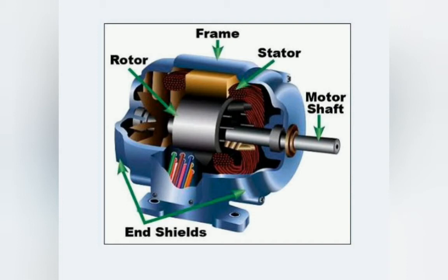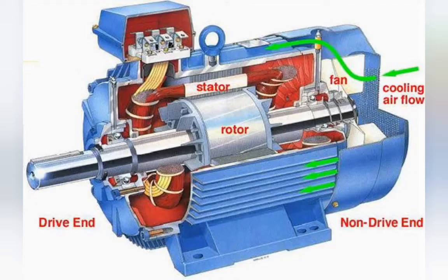The bearings in the motor mainly give support to the rotor to rotate on its axis. The shaft of the motor extends with the help of the bearings to the load of the motor. As the load forces are applied outside of the bearing, the load is known as overhung. The stator in the motor is the inactive part of the electromagnetic circuit. It includes permanent magnets or windings. The stator can be built with different thin metal sheets which are known as laminations. These are mainly used for reducing energy losses.